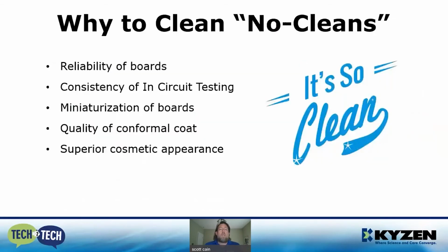So why clean the no cleans? First off, the reliability of the boards. It's going to get everything cleaned off that we've talked about. You're going to have a cleaner board. It's more reliable because there's less chance of dendritic growth. There's going to be a consistency in your in-circuit testing. Some of the no cleans create kind of a putty matter, if you will, after they're processed, and the in-circuit testing doesn't really like that, and there are problems with that.